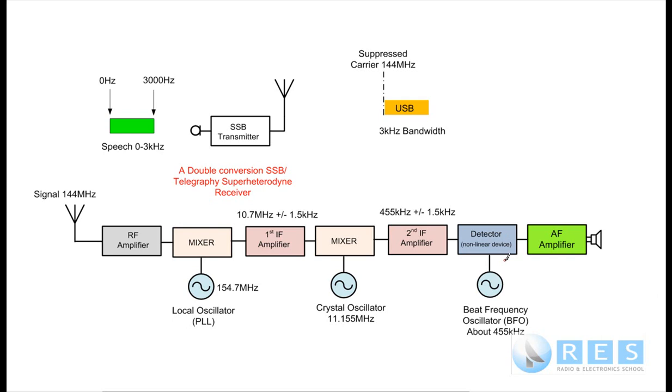That's why the tuning of single sideband receivers is a little bit more tricky than double sideband, because with double sideband the carrier is there and it's on the right frequency and it perfectly converts the sideband back to audio. With an SSB receiver, we have a BFO, a beat frequency oscillator, which we have to adjust to be exactly the correct frequency that the carrier would be on if it still existed.